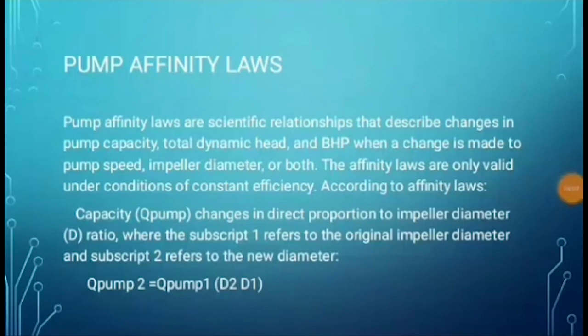Pump affinity laws. Pump affinity laws are scientific relationships that describe changes in pump capacity, total dynamic head, and BHP when a change is made to the pump speed, impeller diameter, or both. The affinity laws are only valid under the condition of constant efficiency.